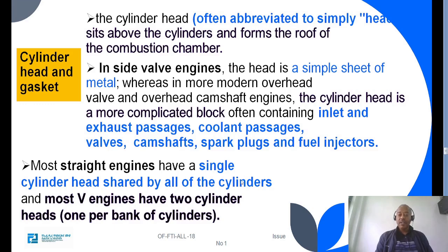Cylinder head and gasket. The cylinder head, often abbreviated to simply head, sits above the cylinders and forms the roof of the combustion chamber. In side valve engines, the head is a simple sheet of metal, whereas in more modern overhead valve and overhead camshaft engines, the cylinder head is a more complicated block, often containing inlet and exhaust passages, coolant passages, valves, camshaft, spark plug, and fuel injector.